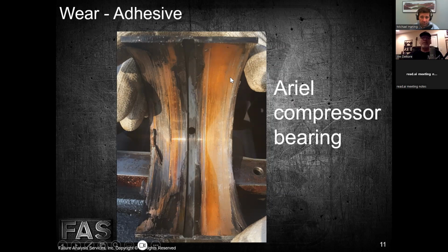So we have the potential of multiple materials that have different melting temperatures. The aluminum or the lead tin both have relatively low melting temperatures, where the copper has a bit of a higher melting temperature. So as that lead tin or the aluminum starts to melt, it starts to pull off. The crankshaft, because of the adhesive wear, is actually adhering to the crankshaft and it's pulling this material off. So that's material being stripped off.